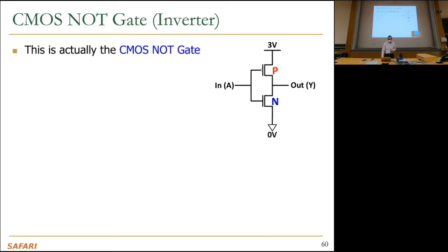And you can see that this is a CMOS technology. You may come up with some different transistor technology. It may work differently, but that's out of the boundaries of this class, right? You go take microelectronics design, you may see different transistor technologies. Unfortunately, none of those are employed in today's systems. Today, we use CMOS technology. People are investigating emerging technologies because CMOS technology is potentially running out of steam, since we've reduced the size of the transistor so much. We're going to talk about Moore's law in a little bit. These transistors may not be working perfectly anymore, as we discussed in earlier lectures. But still, we're using CMOS technology and we're pushing its boundaries.